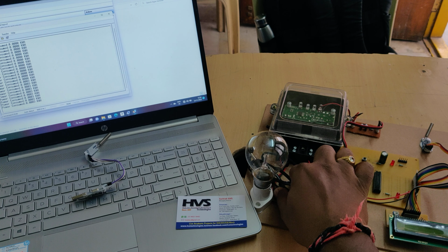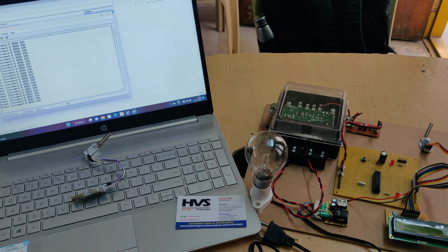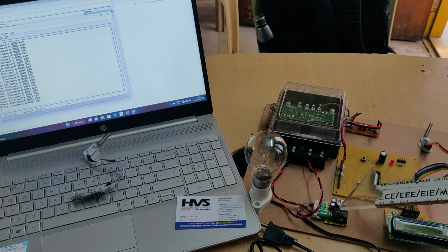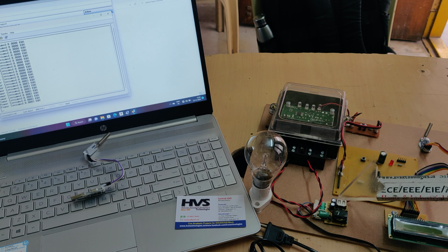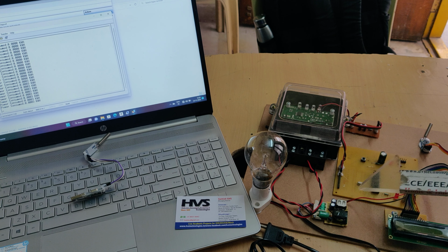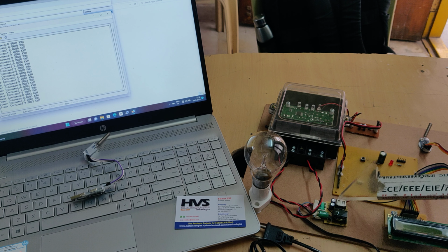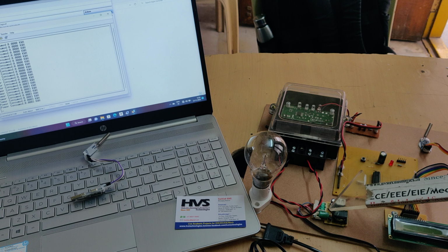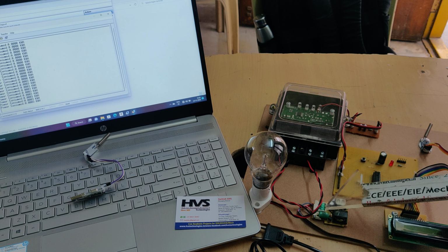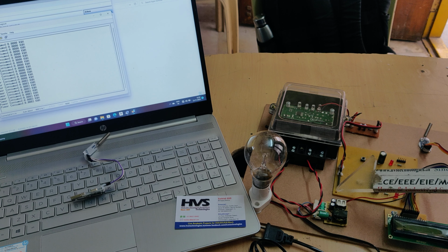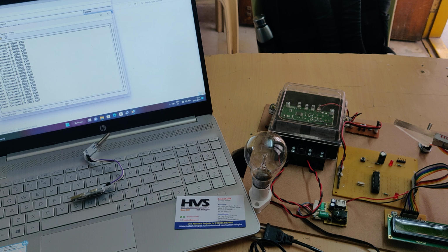So here we are providing 230 volts AC input to this current meter, and parallelly to this regulated power supply board, which has 4 stages: transformation, rectification, filtration, regulation. Transformation steps down the 230 volts AC to 12 volts AC. Rectification converts the 12 volts AC to 12 volts pulsating DC. And filtration converts that pulsating DC to pure DC voltage. So from there we will get the pure DC of 12 volts.